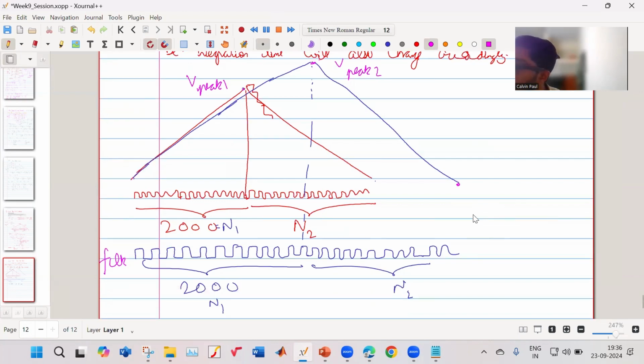But your clock is slow anyway. So the number of clock cycles N2 takes to count in the normal case, as well as in this case, will remain the same. Because the slope and the clock cycles change accordingly, although the clock has changed, the number of cycles remains the same. That is why the error is 0.